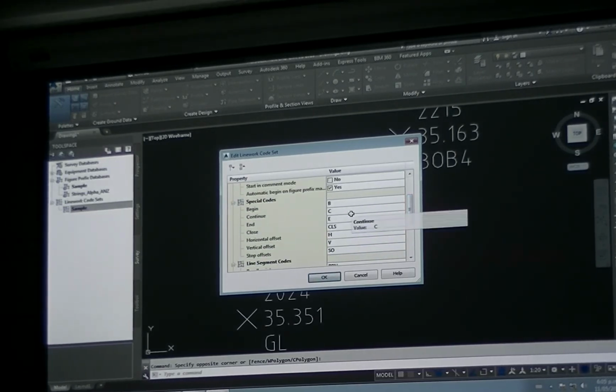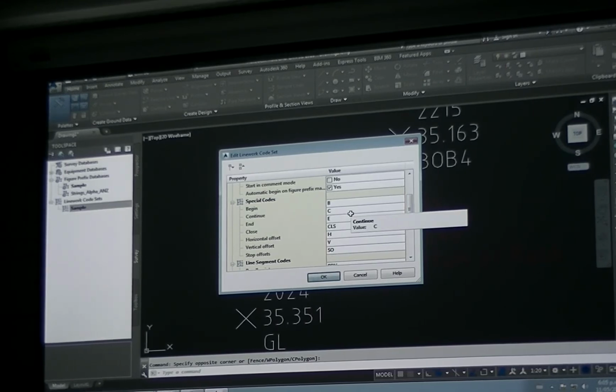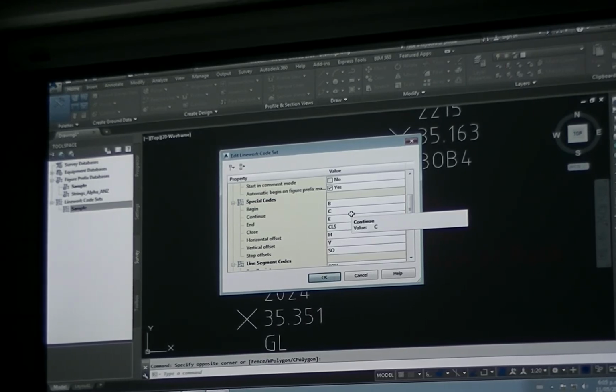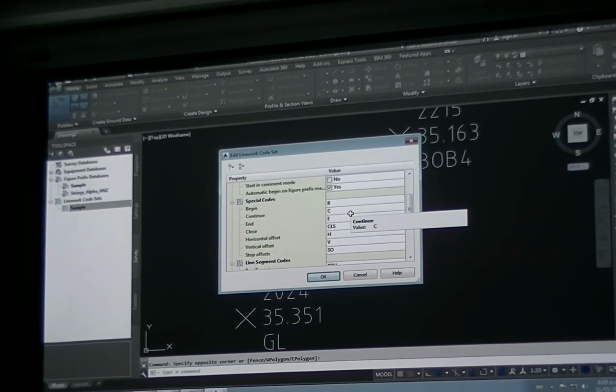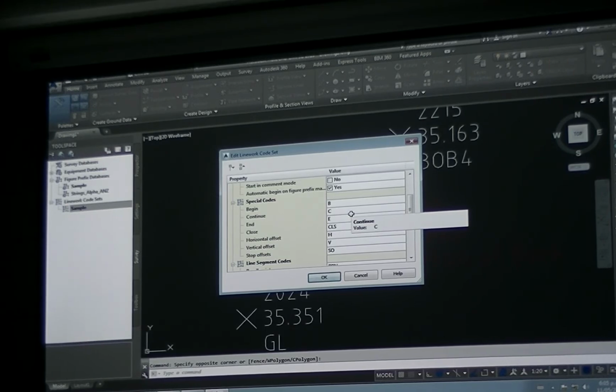The other thing you can do, when you're out surveying, you can be doing a curve. You say you're drawing it in later, you can go start a curve, begin line. Work your way down the curve, and you go end of line. So when you import the data, it automatically draws that curve line for you. That's quite complicated to get into.